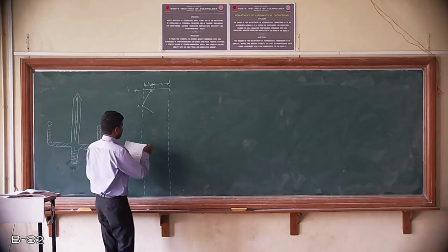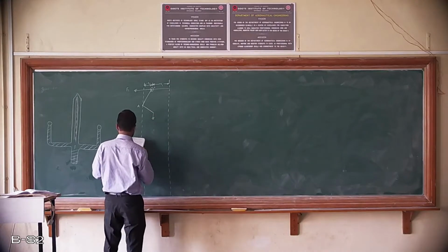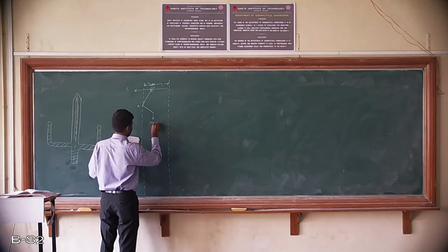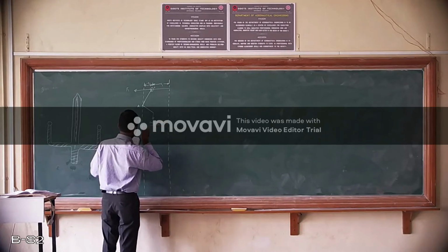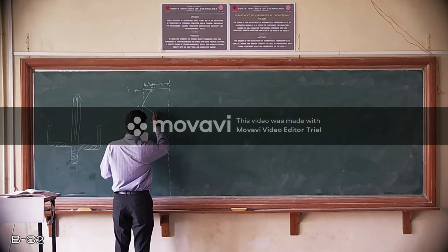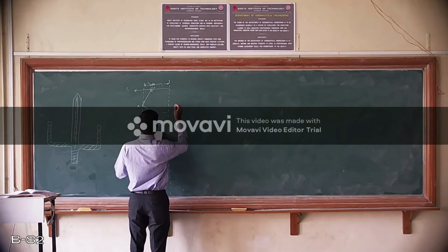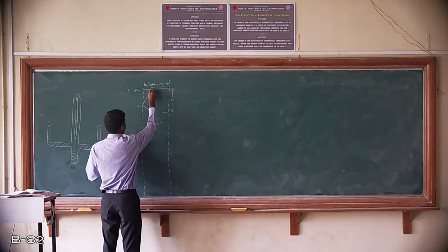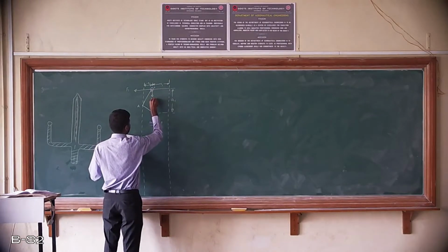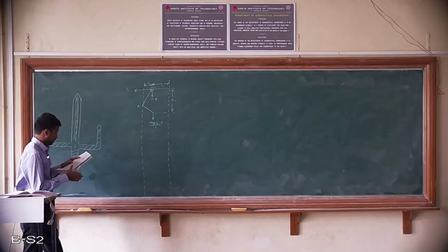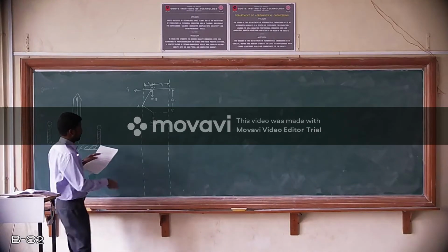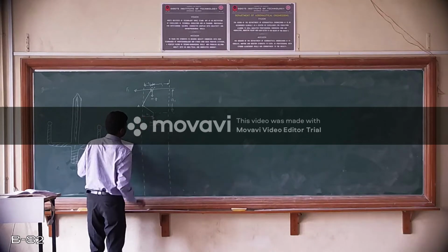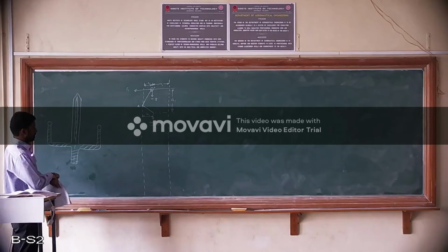The weight of the sleeve will be acting in the downward direction, and it is given by (mg plus fs plus f) divided by 2. I will call this distance A1. The weight of the ball will be acting in the downward direction; I will call this m into g. And I will call this distance B1. So this is for the minimum position.